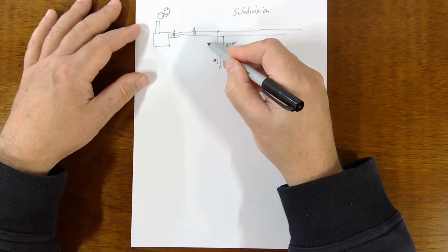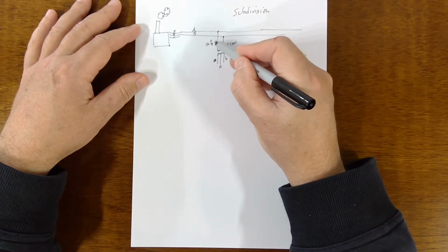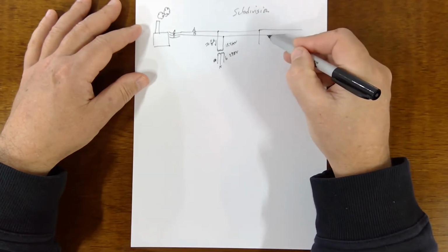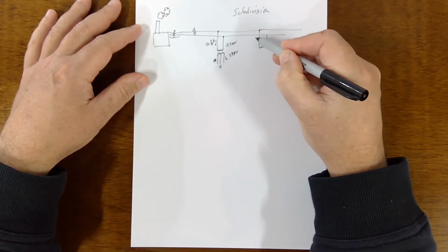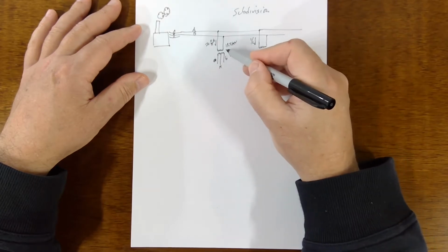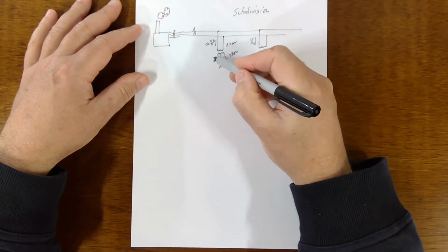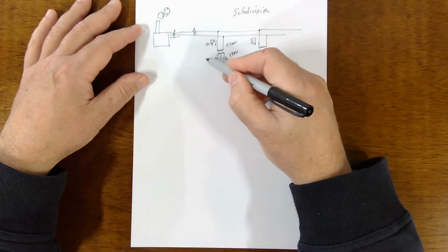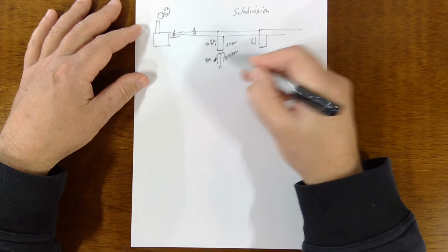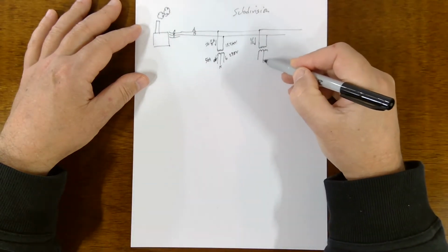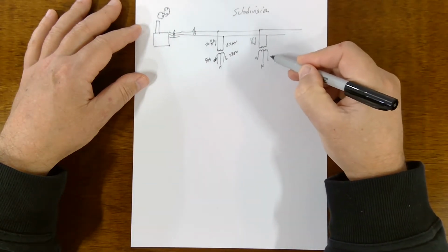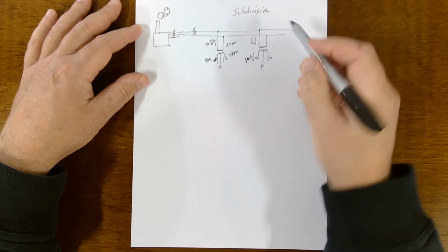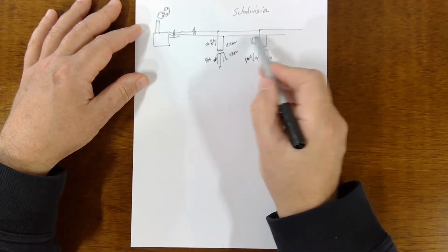And this might be approximately half an amp, right? Very little coming off of here. But there's other houses, and they're all drawing approximately half an amp. Because of this turns ratio, there could be 50 amps in here, 100 times that. And another house, a neutral and AB phase, another 50 amps. So half an amp here adds up to 1 amp.